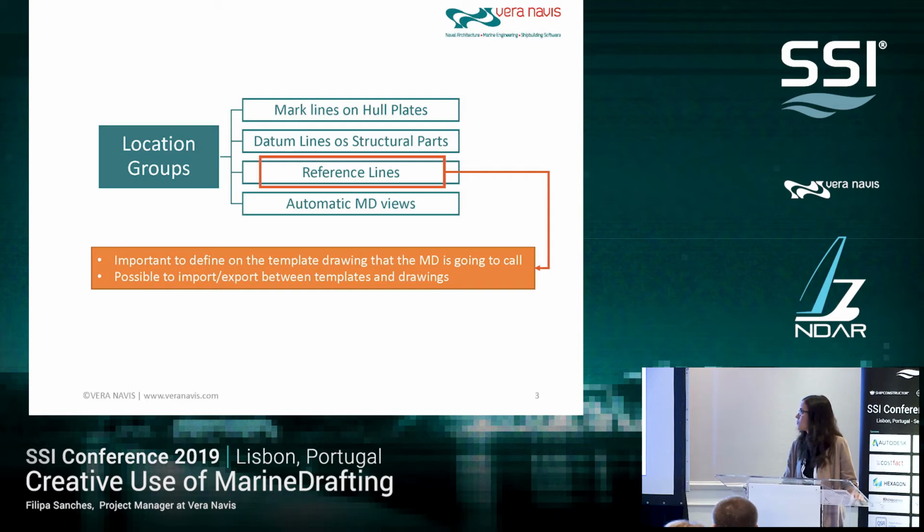About the reference lines, this is very useful, and I know that there are people who don't use this, but please try because you are going to enjoy it. Because you can personalize the reference lines, and it's very easy to create them and to update them. The reference lines can be defined on the template drawing of the marine draftings, and then you can always use it, for example, for the same project in a structure, all the units, all the blocks will have the same reference lines and it will be much easier.